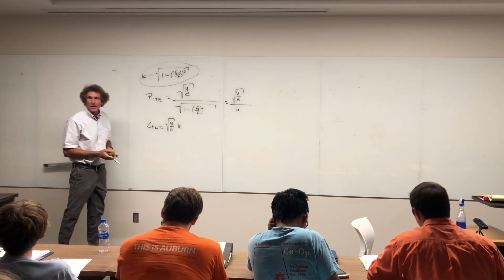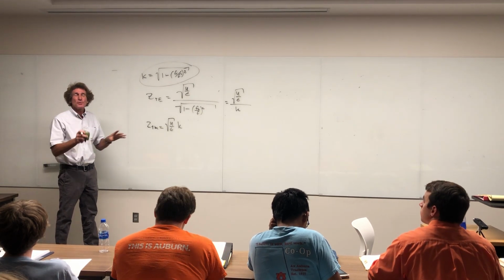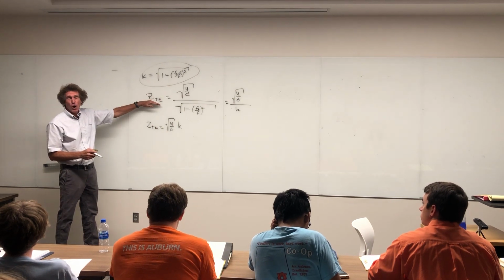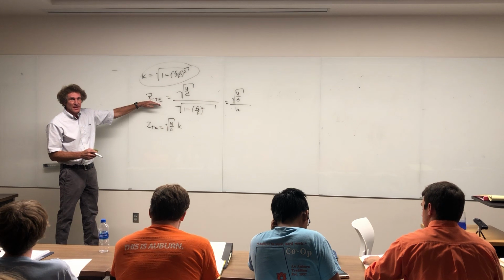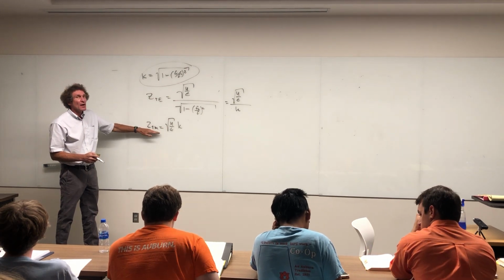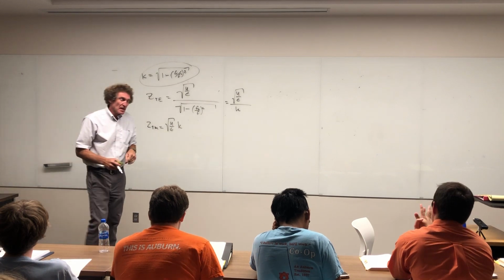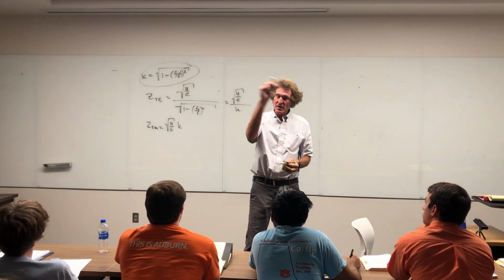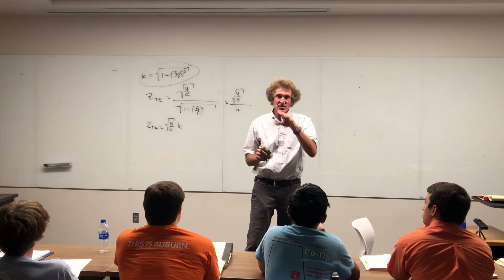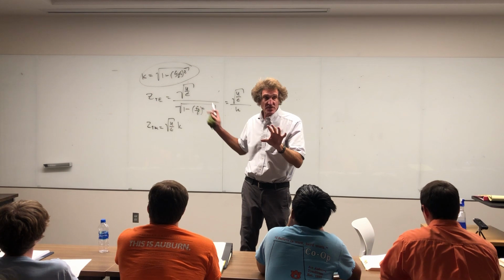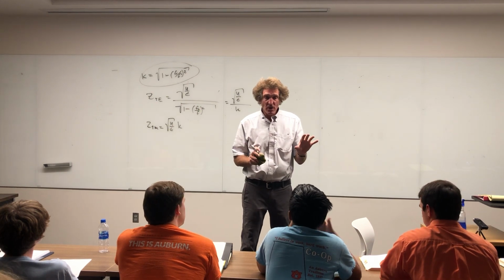Now, me personally, I know there are applications. Most of the time, this is what you use, the 1,0 mode, almost 95% of the time, maybe more. You'll use this once in a while. Now, here's where you use it. Not with rectangular waveguides, but with circular waveguides. He doesn't do circular in his book. In circular waveguides, they do both TE and TM propagation, and the impedances are different. Follow me? We don't have that in the book.